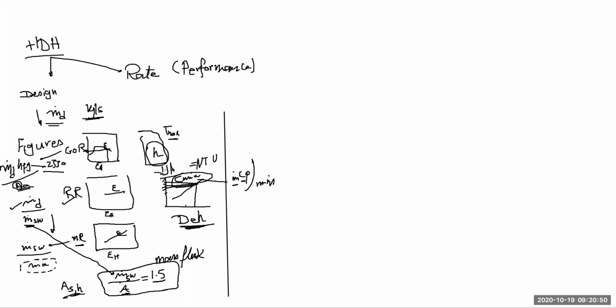The overall heat transfer coefficient would be given to you. The number of transfer units you can get from the figure, then you can calculate the area. So if the figure is not given, I can use this formula and we'll get the same number.